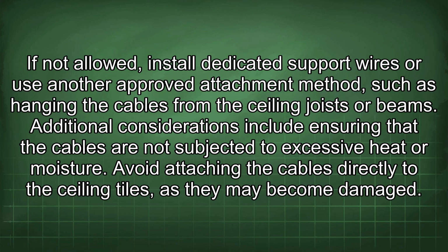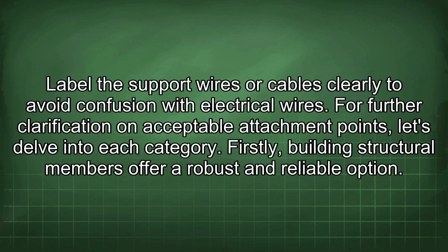Avoid attaching the cables directly to the ceiling tiles, as they may become damaged. Label the support wires or cables clearly to avoid confusion with electrical wires. For further clarification on acceptable attachment points, let's delve into each category.